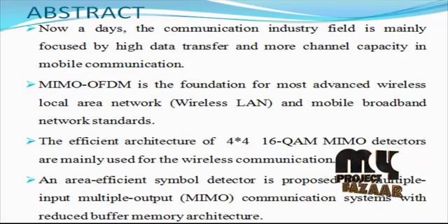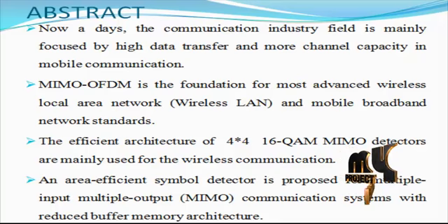The Third Generation Partnership Project defined Long-Term Evolution to meet the requirements of 4G wireless communication. LTE combines multiple-input multiple-output technology with orthogonal frequency division multiple access technology in the downlink and single carrier frequency division multiple access in the uplink to achieve peak data rates up to 300 Mbps and 75